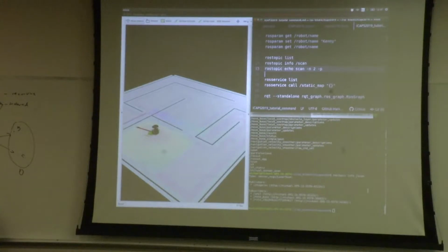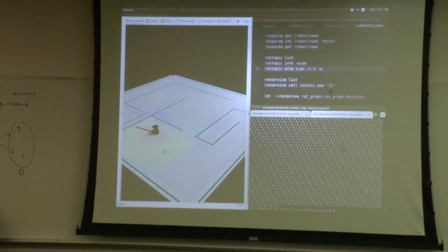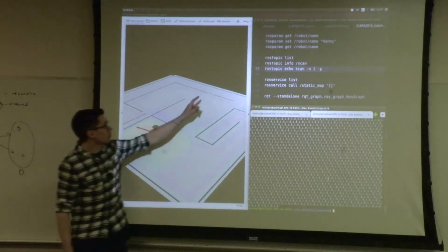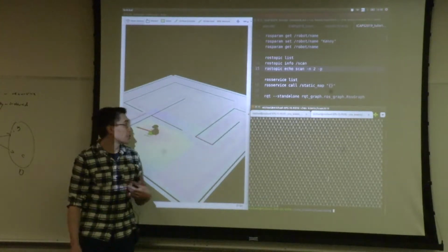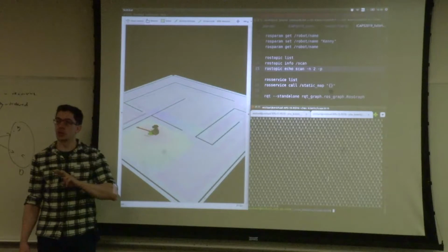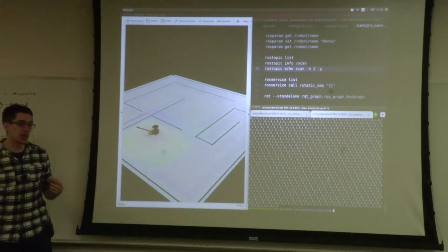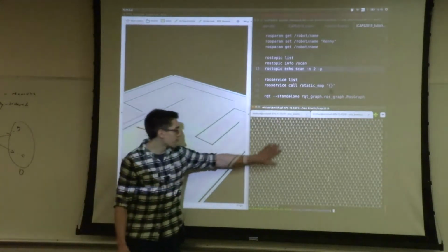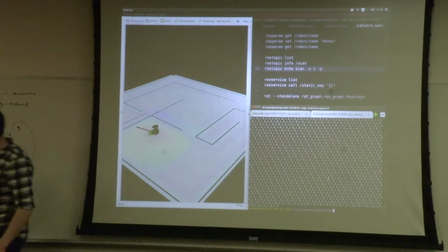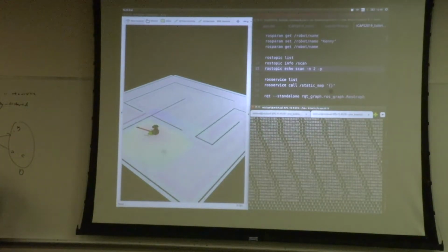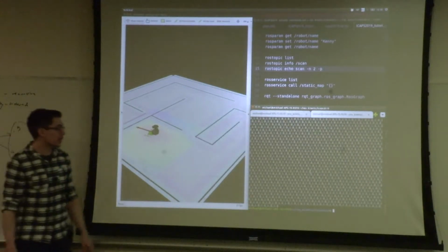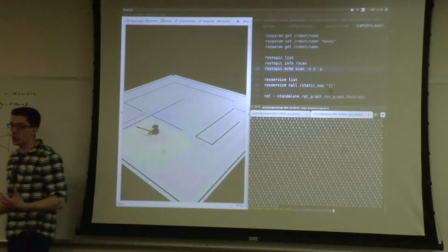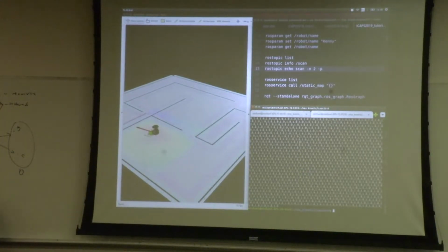And we can have a look at the scan. So the line I just ran there, rostopic echo, just prints the messages being sent on that topic. -n 2 means only print the first 2 messages, because these are being printed at quite a high frequency. We don't want to have a look at all of them. And this is the scan. Just a lot of data, basically. And at some point, we need to figure out how to connect this to our planning model so that we can understand what is the current state.